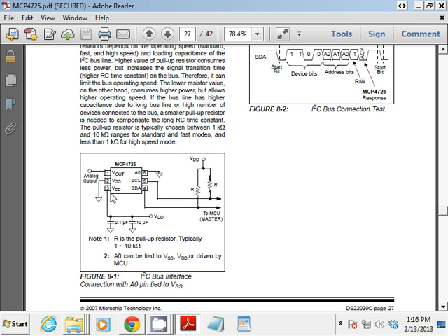The wiring of your little chip is usually straightforward. These are pull-up resistors for the bus. You'd probably only need one resistor per wire, and that's it. You wouldn't need one for every peripheral. The bypass capacitors are probably good to try and damp out some of the noise that might be on the power supply.